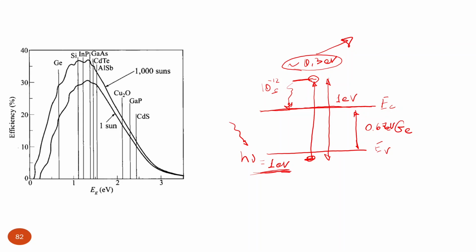So as a result, we get this curve with a maximum, and there is some sweet point where we have high enough VOC and low energy losses, but still we absorb quite a decent part of the solar spectrum and can maintain quite high short circuit current, and that is in this region of maximum of this curve, which corresponds to a band gap of about 1.5 electron volts.